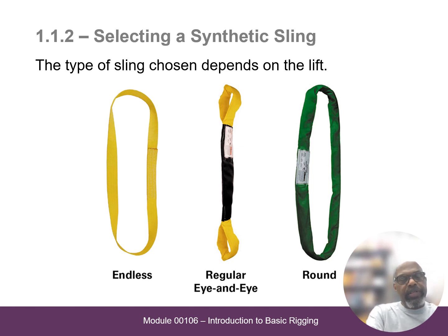These are different types of slings. The first one on the left side, they call it endless, just a loop. The one in the center has been attached together, but is joined in the middle. However, most of the slings you would see and use would be like the endless. They do make the round one. The round one is not truly round, but it's an oval shape compared to the endless, which is flat. It lays flat, and it's pretty nice how it lays flat when you're lifting something, especially something square or rectangular.